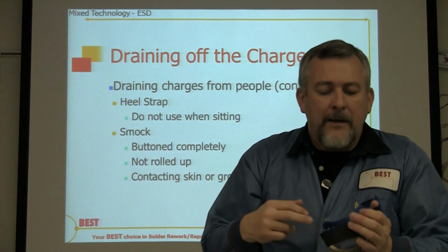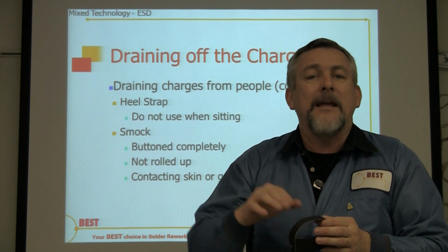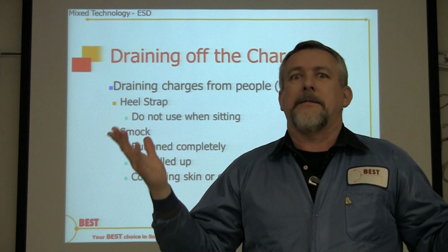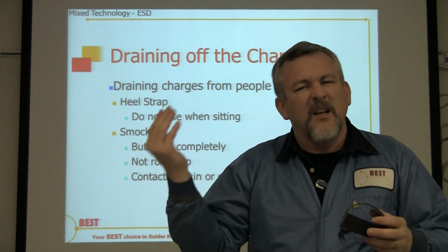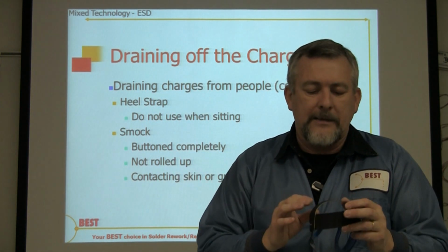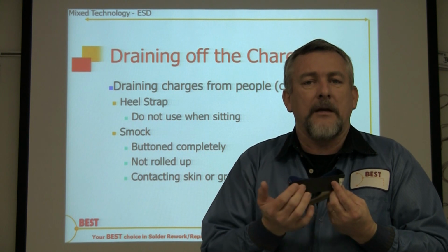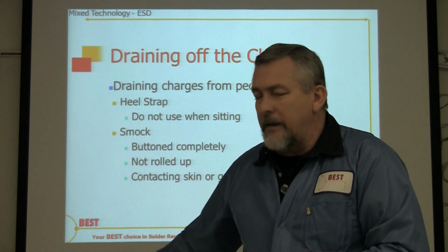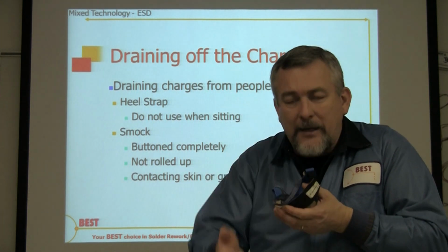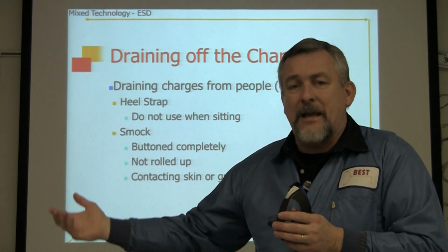Very simple. Now, one of the things about these that I see people doing a lot of times is they walk outside, they take their coffee breaks, they take their cigarette breaks, or like today, it's very nice out, they want to take a little bit of a walk because it's getting off the wintertime, spring is here, feels so nice out there. So, what do they do? They get dirt and contamination on here. So now, when you're walking on that ESD safe flooring, guess what? It doesn't work. It's not creating a path anymore. So that's why you should never wear these outside or off an ESD safe floor.